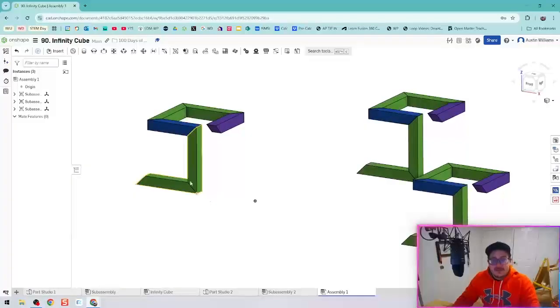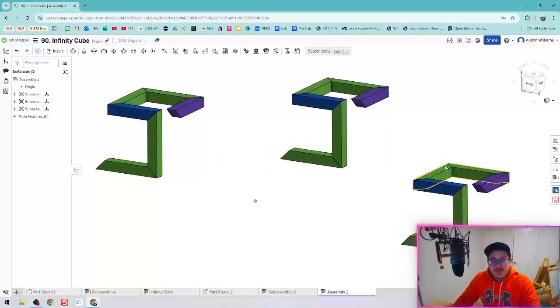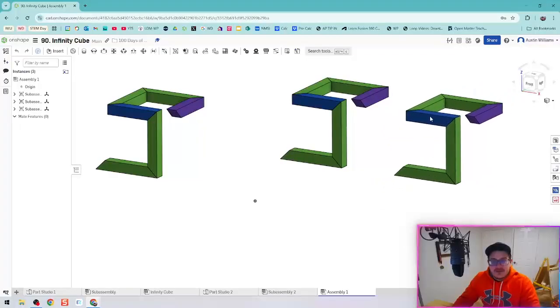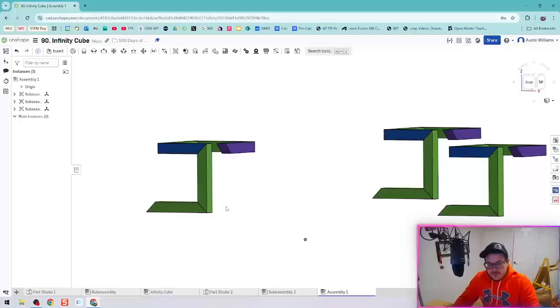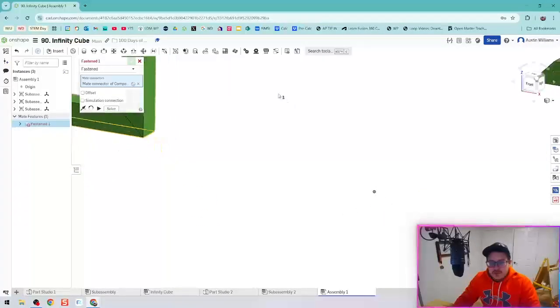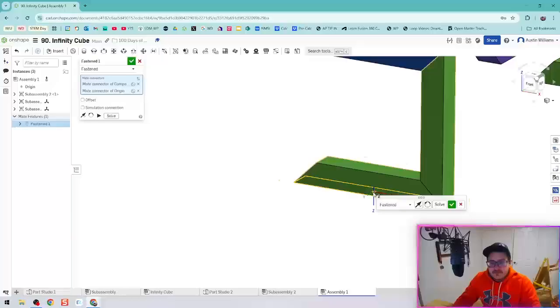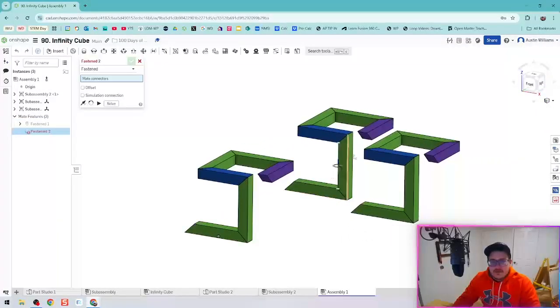And now we're going to notice this is just like the composite parts. Subassemblies move together, not independent of each other. How much time would we use doing all those mates to make that work? It would just be a really long time. So I'm going to hit M for mate. We're going to mate our first part to our origin. Looks good. We're ready for our next mate.